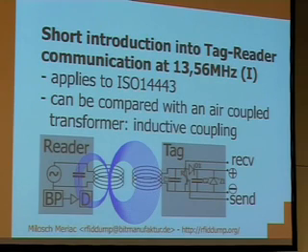So you actually get a higher load on the tag side, and on the reader side, because the reader needs more energy to keep the magnetic field up. And if the send line is triggered in this case, you get this shortage and you see an amplitude change on the reader side. On the reader side, you see this BP part of the schematic, and the BP makes sure that only this amplitude change is filtered out of the signal by a bandpass, and it's demodulated.